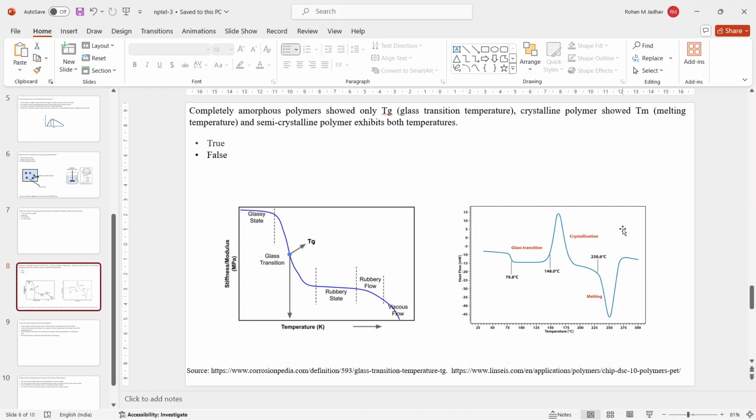So you have this. And on the left hand side, you can see how the property of the polymer changes with respect to temperature. When we are at the lower range of temperature, the polymer is present in its glassy state. As you increase the temperature, you see the transition zone, and then we get to the rubbery state where the polymer becomes extremely flexible and starts flowing and stretching around, and then viscous flow is initiated as the temperature increases. Basically, your polymer has already melted.